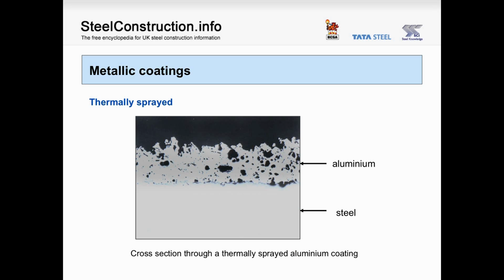The adhesion of sprayed metal coatings to steel surfaces is considered to be essentially mechanical in nature. It is essential to apply the coating to a clean, roughened surface, and blast cleaning with coarse grit abrasive is normally specified. No alloying occurs and the coating consists of overlapping platelets of metal and is porous. The pores are subsequently sealed by applying a thin organic coating which penetrates into the surface. Sealers may be either unpigmented or with colouring agent or aluminium flake.